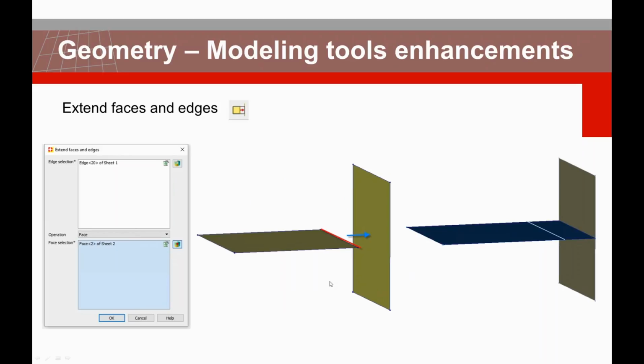If you remember, with respect to IFC, I was telling that if you import your reduced geometries, you may have some sort of gap because of the presence of your neutral axis. So everything is going to be reduced from solid to sheet, and these will be located at the neutral axis. Therefore, there might be some sort of gap.